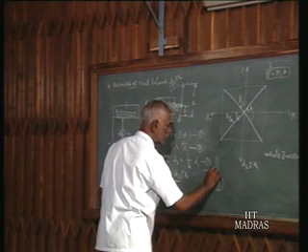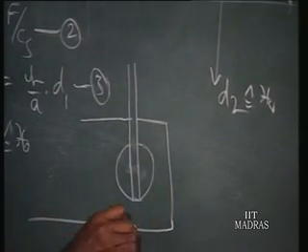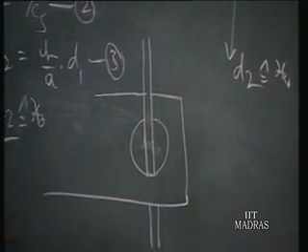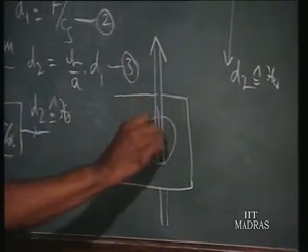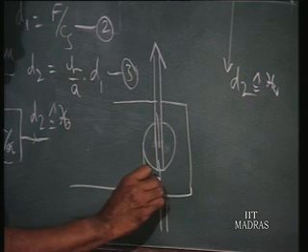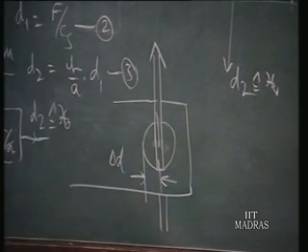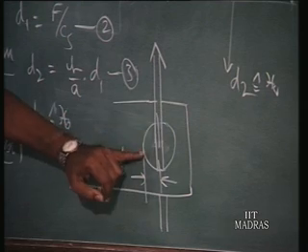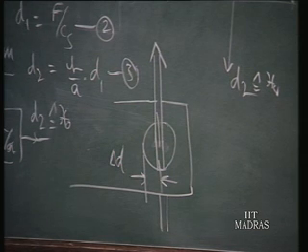This is our piston rod end, and this is your pointer that goes to the pivot. Suppose in the middle position we have got some play. I will call delta D the play. Until delta D is overcome, there is movement but the pointer is not going to rotate. So delta D becomes an error in this instrument.